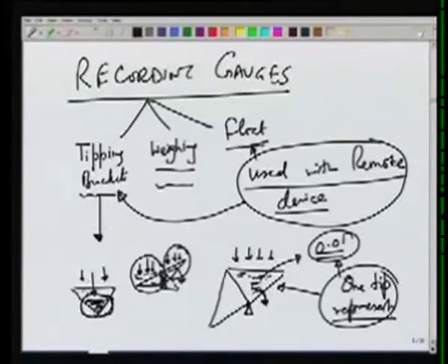And when next time there is some rain which occurs, it will fill the bucket and will tip it, and therefore the rainfall will be recorded as occurring at some other time. So tipping bucket is a recording type of rain gauge because it will record continuously what is the time it takes to fill certain capacity.